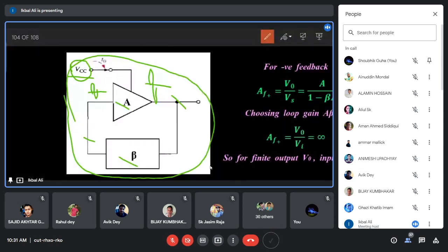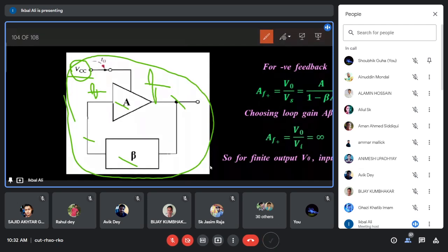That noise may be anywhere in this electrical circuit, very small fluctuating voltages. I don't know whether you have the idea of electrical noise. It may vary. The current you have designed for the amplifier, suppose 1 milliampere, may not be constant. Usually it is not constant. It may fluctuate, a very slight fluctuation. You cannot make it ideally 1 milliampere. The number of electrons per second flowing for 1 milliampere current may not be the same for every second.